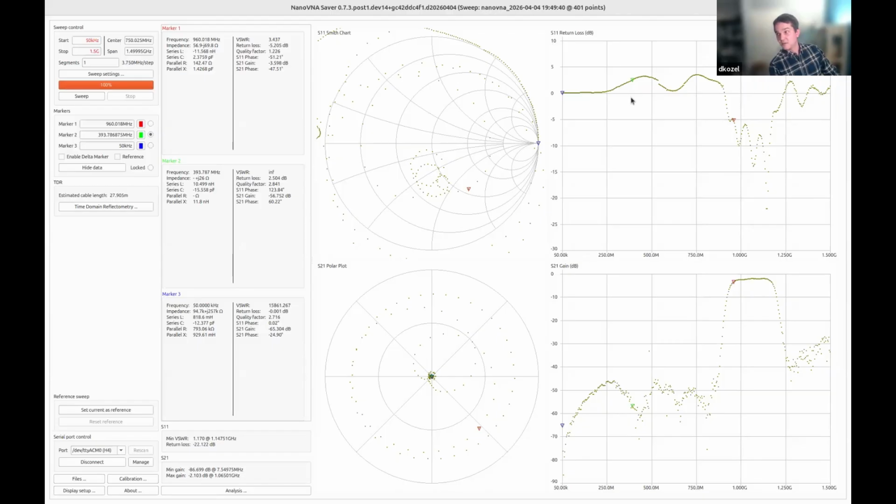But what could be going wrong at this point? I've looked at this plot and I've said, okay, the band pass seems to be working pretty well. I believe that this has told me the frequency that it will work at. Great. It is showing me that it is attenuating signals out of band. Great, I believe that. This general shape of the noise floor, or the gain floor, is following what it was when I just had my calibration loads there. I believe that.